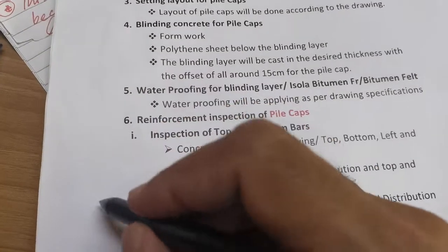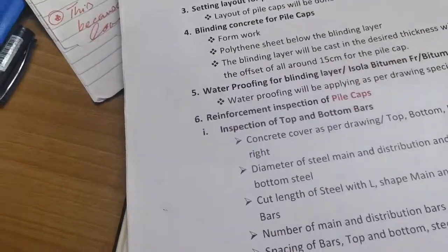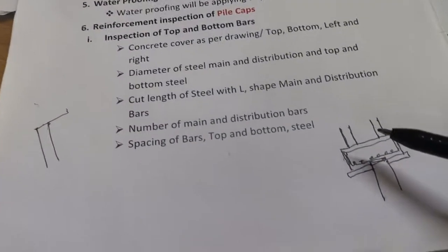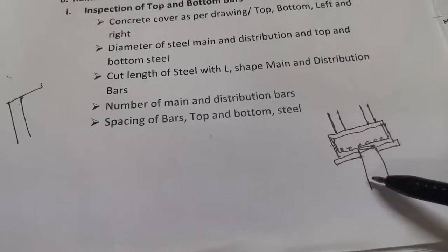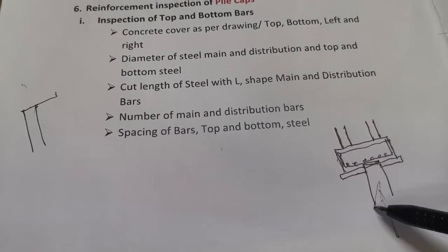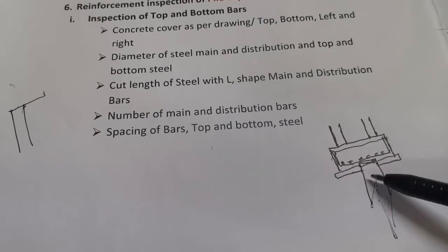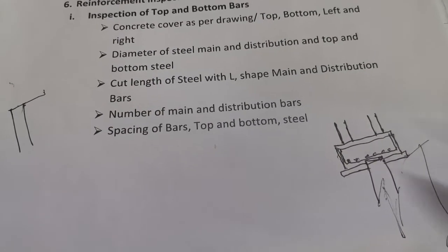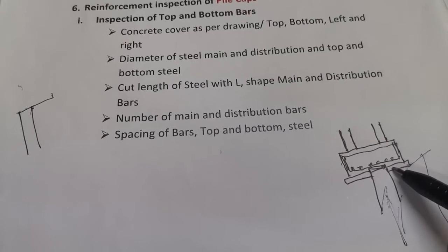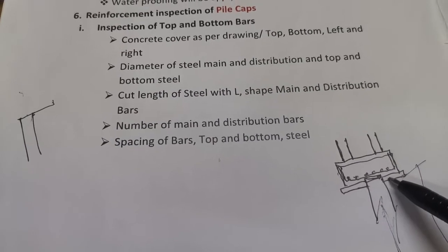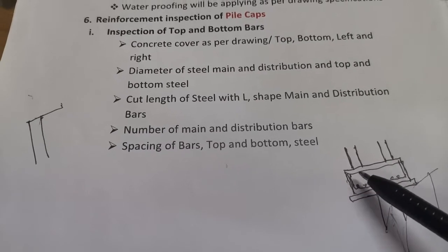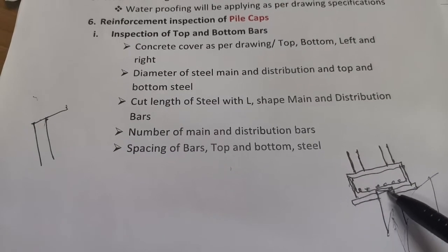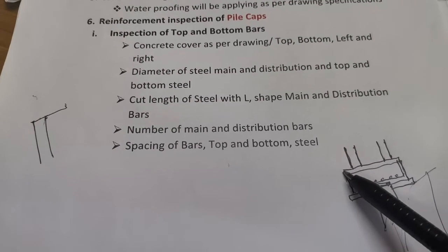I'm saying, suppose that I will draw the section first. Yes friends, I am doing AutoCAD work also quickly. Here you can see this is the pile cap. Okay, break line, 13 meter depth of pile. Then there is the blinding PCC. This is the cut level. This is plain cement concrete. Then they will do the shuttering for the pile cap. This entire thing is the pile cap.